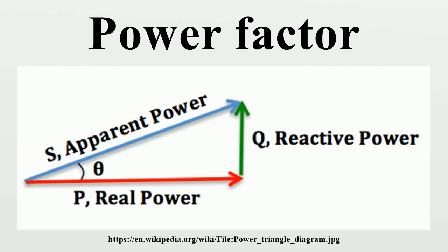As power is transferred along a transmission line, it does not consist purely of real power that can do work once transferred to the load, but rather consists of a combination of real and reactive power, called apparent power. The power factor describes the amount of real power transmitted along a transmission line relative to the total apparent power flowing in the line.